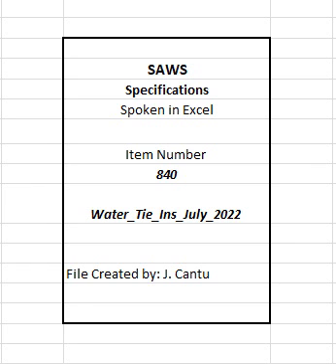840.5 Construction. The contractor shall make tie-ins from new water mains to existing water mains as shown in the contract documents or as directed by the engineer. 1. The contractor shall be responsible for all shutdowns and isolation of the existing mains, cutting pipe for the connection, dewatering the excavation, advance customer notification of the shutdown, and all other requirements as directed and coordinated through the SAWS inspector to provide completion of this effort in a safe and secure manner.